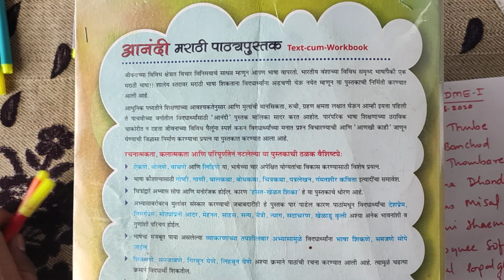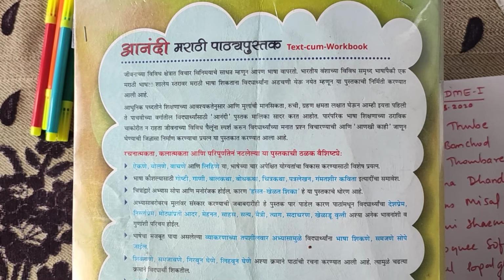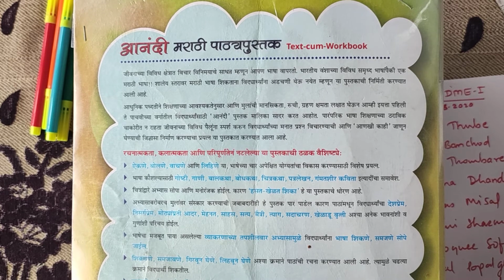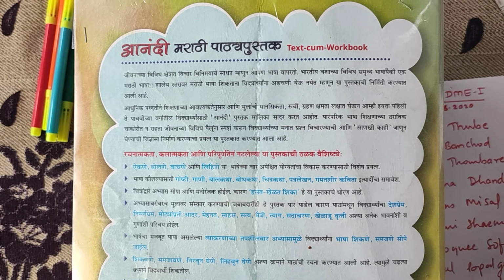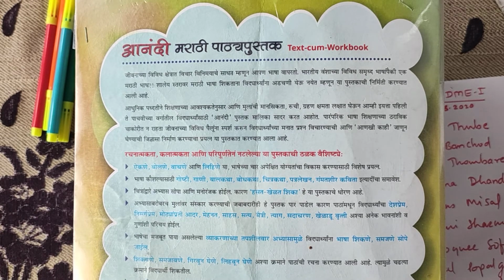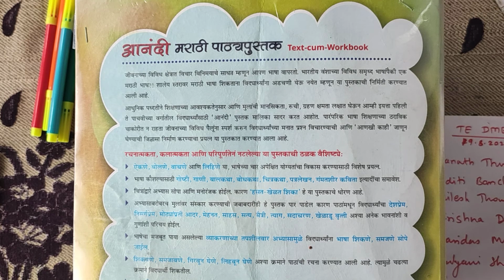For the bending, you have to consider the distances of capital D1 and small d1, and force P. Considering that, you find the maximum bending moment M, and then considering the section modulus, we can find the maximum bending stress, and using that you can find the maximum dimension of the cotter width B. So that is the 10th one. I hope you got this.